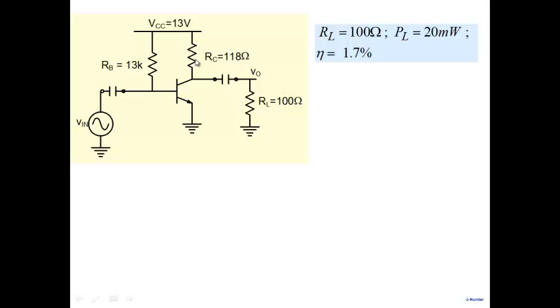Now, if you're thinking, this is what might occur to you. Here is an amplifier, and this is its performance. So if you calculate the gain of this amplifier, how do I calculate gain? I know ICQ, so I know GM, and GM times RC parallel RL is a common emitter amplifier. So you calculate the gain and you get a gain of 192, right? And now something should start working in your mind if you see this number.